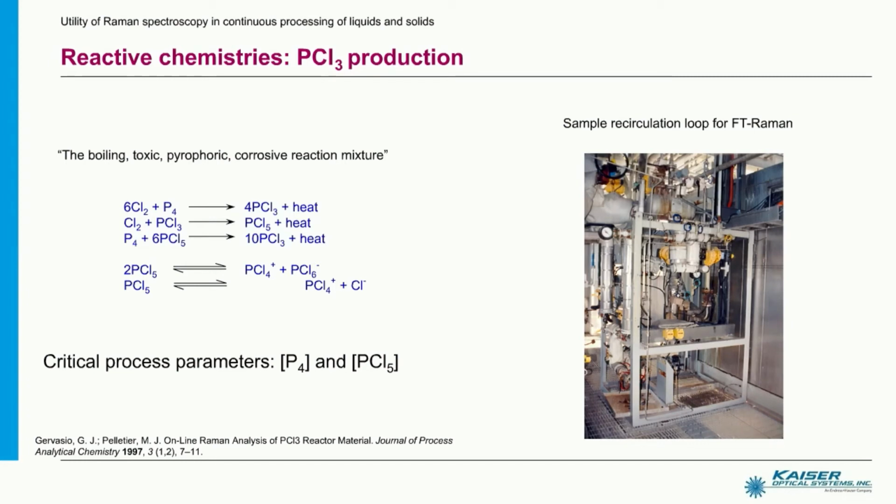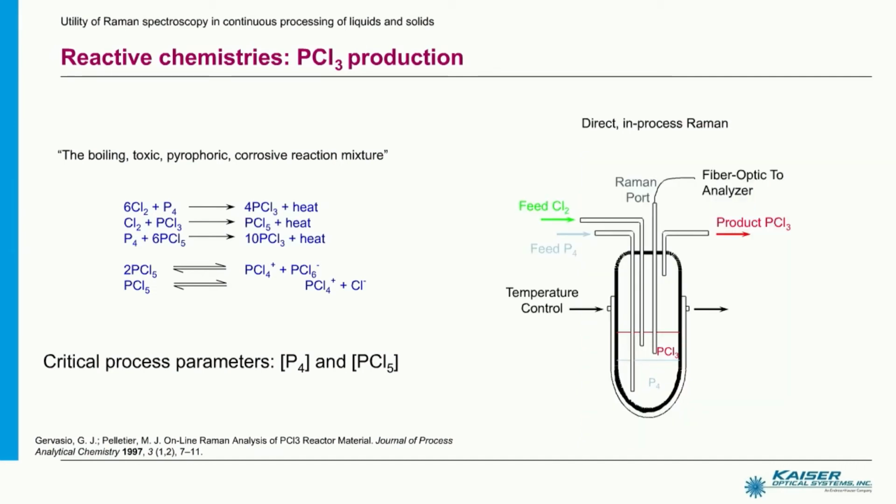Raman via a sight window. But the in-process implementation required a recirculation loop, and that sight glass still needed to be cleaned due to opaque impurity buildup. The analysis time was about 5 minutes, and it required 500 milliwatts to 2 watts, which meant sample heating and window damage. Moving to dispersive Raman, they got an in-situ measurement in 30 seconds using 40 milliwatts of power. The sample heating generated by that 40 milliwatts had no effect on the sample.